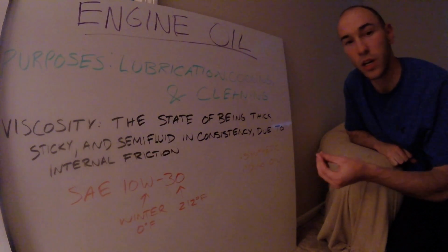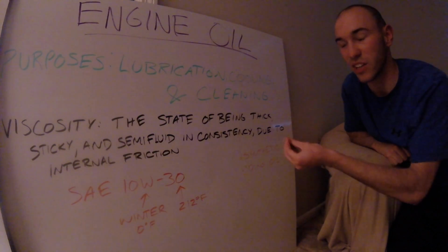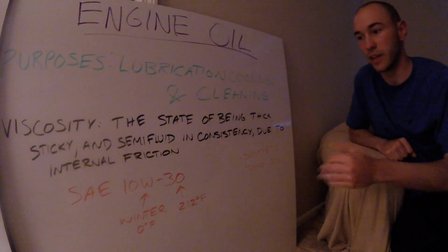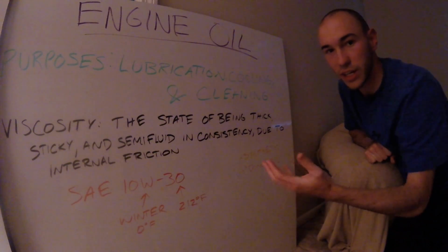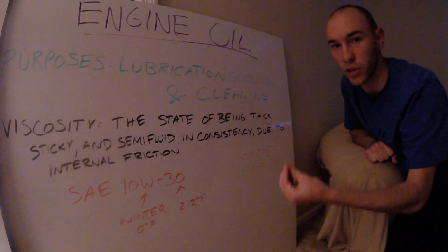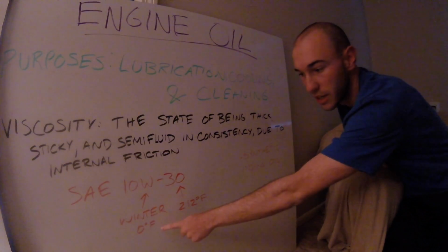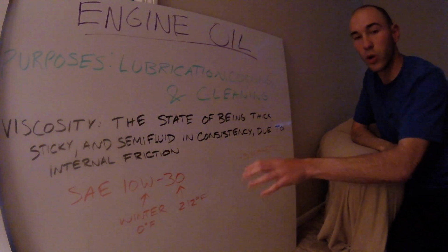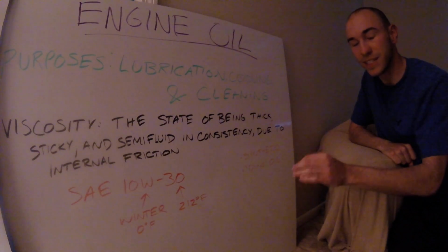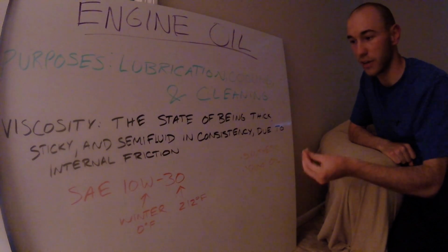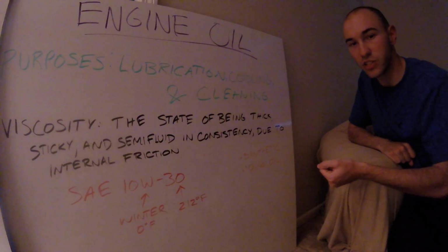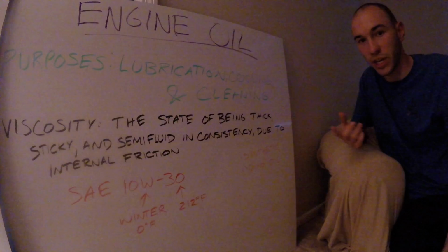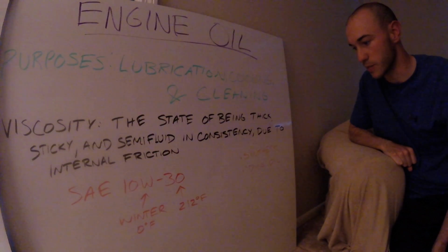The higher the number, the more viscous it is, the more of a solid it acts like. You might think intuitively that a colder liquid will congeal more and therefore should be more viscous, so at a lower temperature it should be a higher number. But the oil is specifically designed and blended to be thinner at a lower temperature. That way, when you're starting up a cold engine, you have very thin oil that's easy to pressurize and move through the system quickly to lubricate and do its job as quickly as possible.